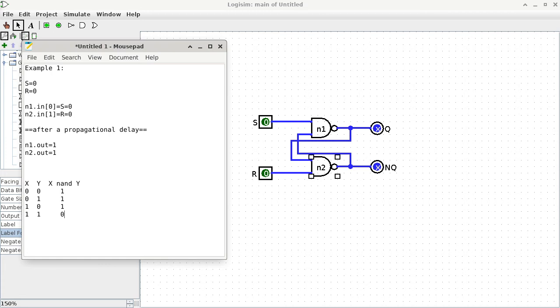So you look at this, and then you say, well, if we already know one of the inputs, it doesn't even matter which one is a 0. If X is a 0, the output is guaranteed to be a 1. If Y is 0, the output is also guaranteed to be a 1. So that means if I just know one of the input pins of a NAND gate is a 0, the output is guaranteed to be a 1. I don't even need to care about what the other input pin has to say. Is that okay? So this is an application of a truth table to visualize why I can make that deduction that I did make a little bit earlier. Are we good so far?